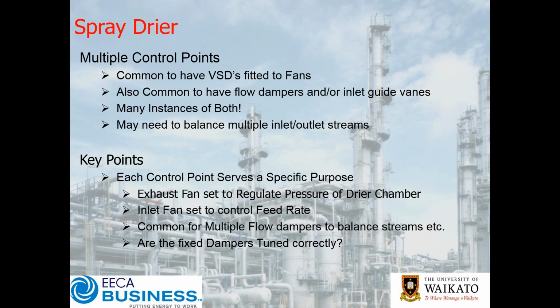Okay, and remembering that each control point serves a specific purpose. And then once you understand how those things are working correctly, we can then start to look at, can we eliminate a number of multiple flow dampers, for example? Have we got fixed dampers tuned correctly? Is everything where it should be? Have we got extra blockages in the system that we shouldn't have? Are there things impacting on the performance of our system that we can look to retweak?